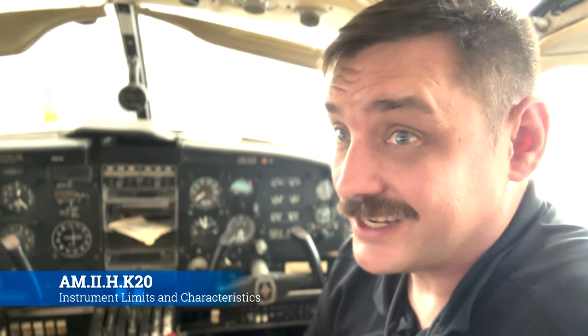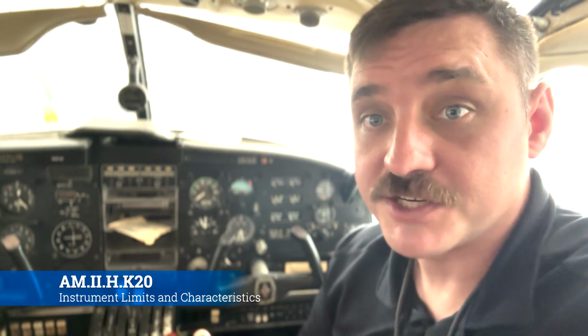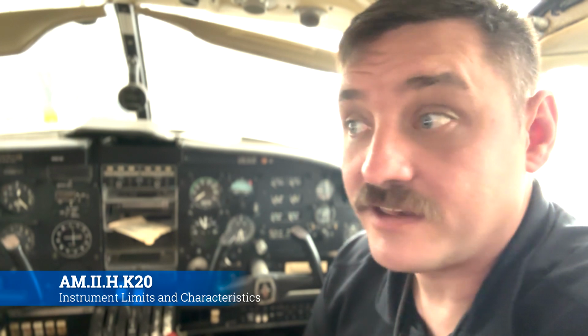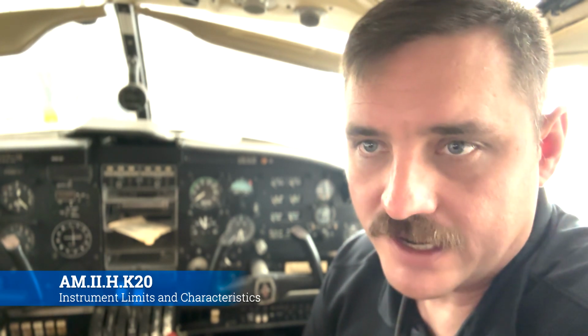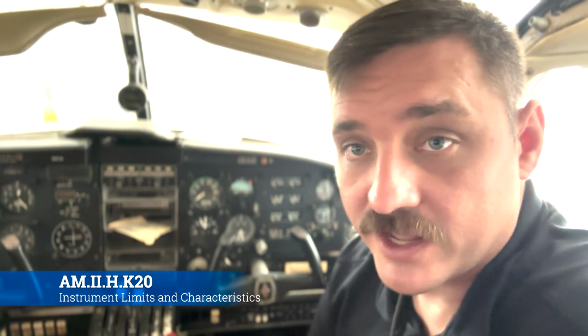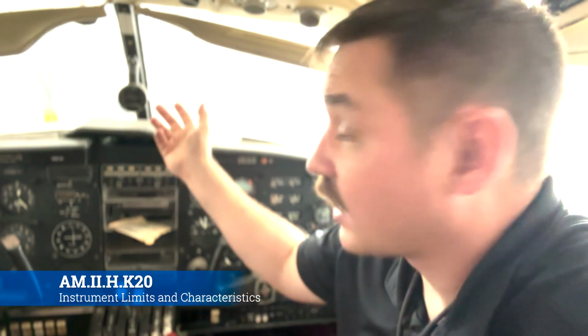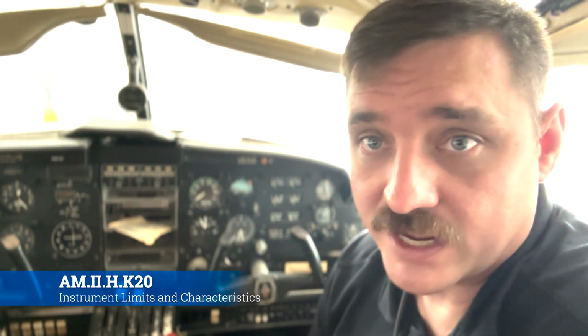Now, if there's something going on in the outside world, let's say there's icing out there that could potentially clog a static port or a pitot tube, then we need to take that into account whenever we get instrumentation failure or some sort of wacky reading that we know is not right. There's also other things that can affect things. If you turn on the radio, it's going to have an effect on the compass because you're emitting electromagnetic interference into the area that the compass has to operate in. So we have to take that into account.